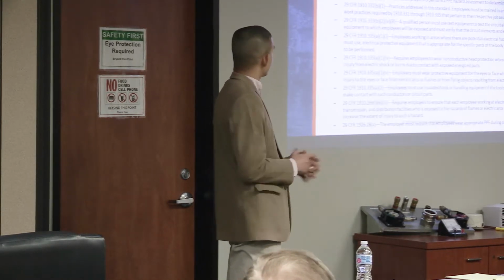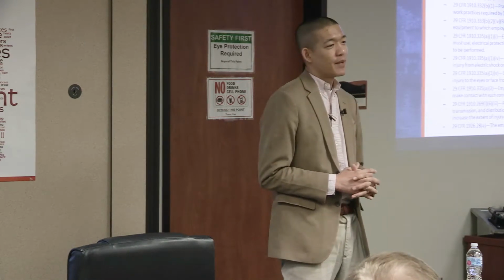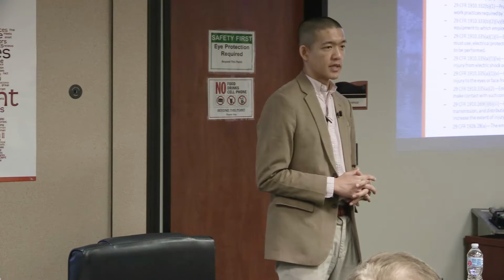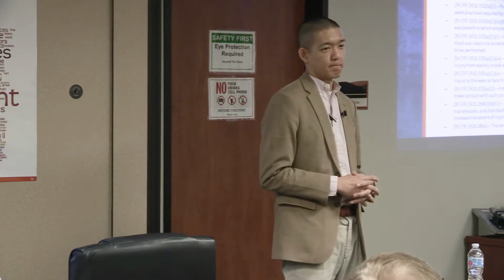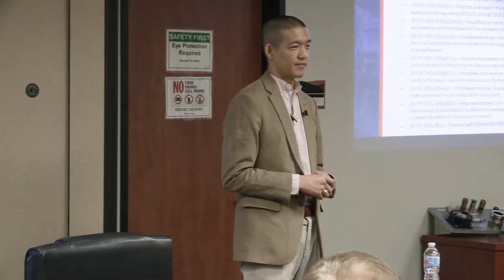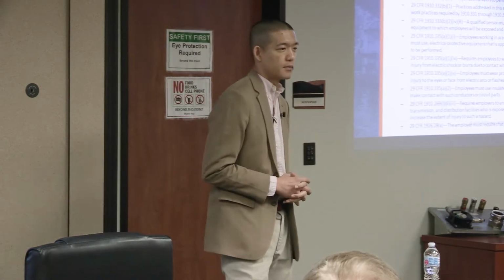So, what's your end result? Does it tell you where you have the highest potential of an arc flash? It does. Or actually, all the places that you have the potential? Basically, any piece of electrical equipment, whether it be a panel board, switchboard, switchgear, disconnect switch, or VFD disconnect, we label all of those. If somebody can peek inside that piece of equipment while it's live, then we're going to put a sticker on there. If they can open it while it's live? Mm-hmm. Okay.